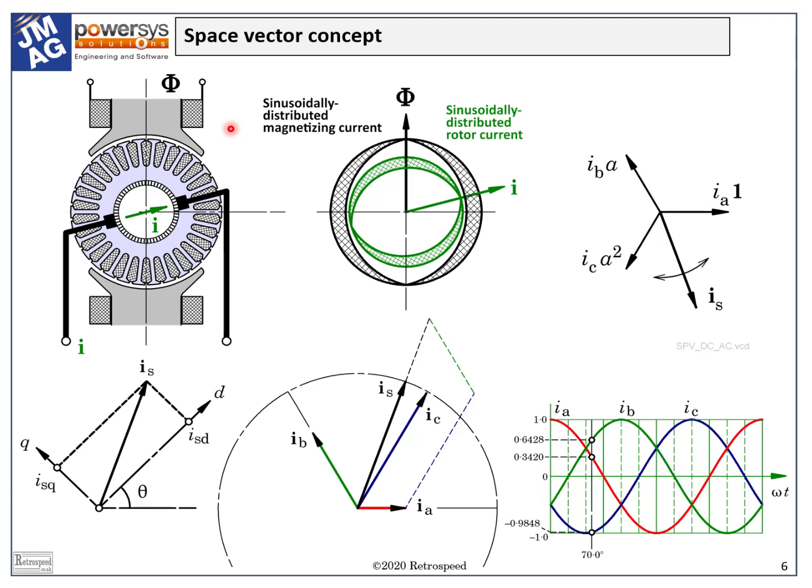Thirdly, the flux in a DC machine has a more or less rectangular spatial distribution around the armature, whereas in the AC machine we're concerned with the fundamental space harmonic component, which of course is sinusoidally distributed. The shapes of these distributions are of course vital in the design and operation of the respective machines, but for our purposes they do nothing more than give rise to coefficients which appear in the performance equations and then are seen no more.